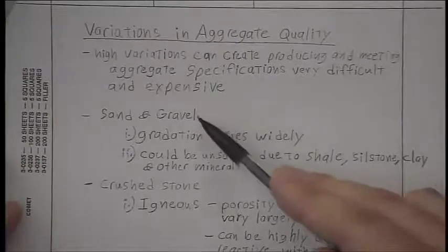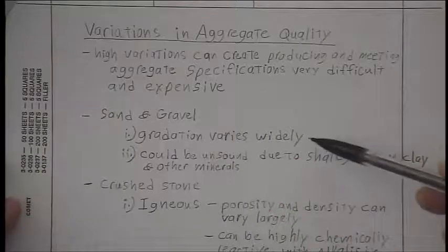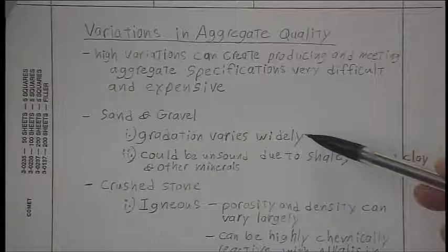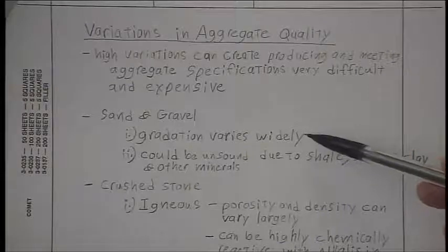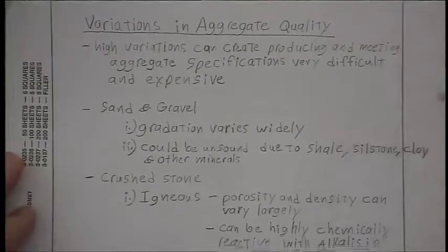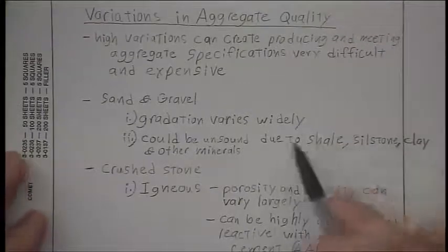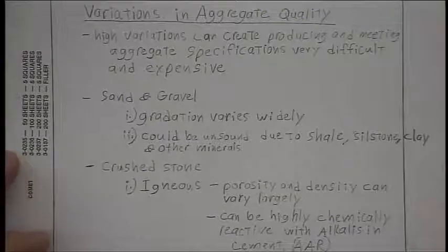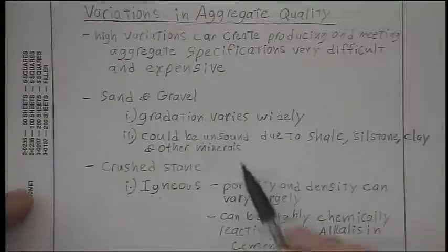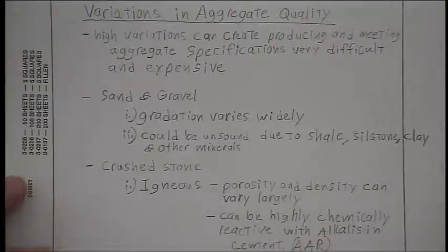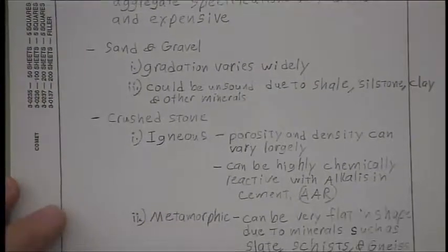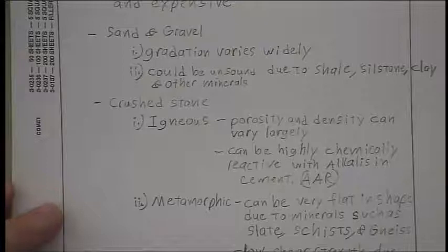Just in general, with sand and gravel, the gradation varies widely. It even varies depending on when it last rained. So you have to understand, on that river source, or if it's dry, where your gradation actually is, and if there are too many clays and other bad chemical impurities that make your source undesirable.